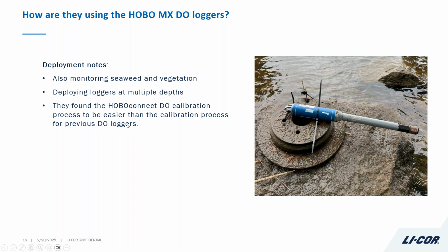They were deploying at multiple depths, and one of their comments back was they like the calibration routines that are built into HOBO Connect, making it easier to calibrate the DO sensor in these than with previous loggers.